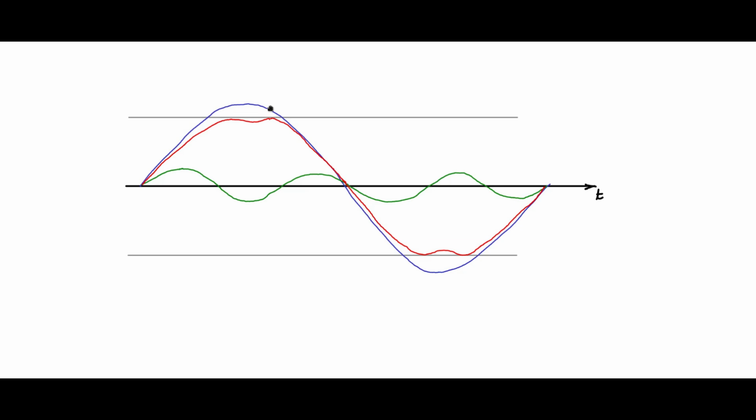So in space vector modulation we use this technique of trying to get more fundamental out of it. A normal sinusoidal will give you just about 100%, whereas space vector PWM, because of this, can give up to 114%. So that is the extra mileage that you can get. That is why a third harmonic is added.